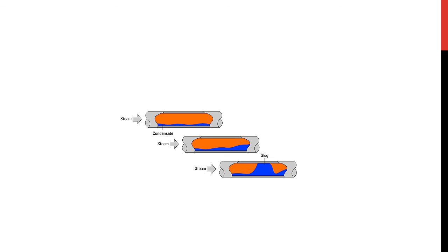Okay. So if you look at those, this is kind of the analogy inside the pipe. What happens? Steam goes in, water comes back. The water is in the bottom. This is steam. And what happens if you have too much water? You have a wave, and you will have a pocket of steam in here that eventually will try to sneak its way through the water, and eventually cause you to have a small bang and hammering.